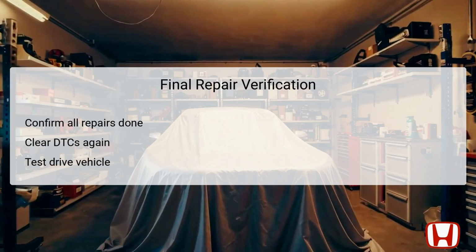Finally, conduct a test drive of the vehicle under various conditions to confirm that the issues have been resolved and that the engine runs smoothly without further indications of injector circuit malfunction. Monitoring the vehicle post-repair allows technicians to ensure that the repairs made effectively addressed the initial problem.